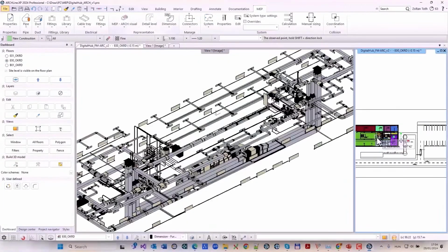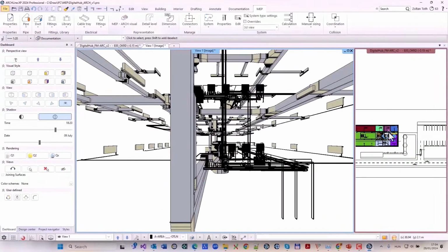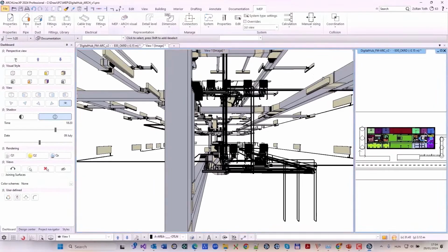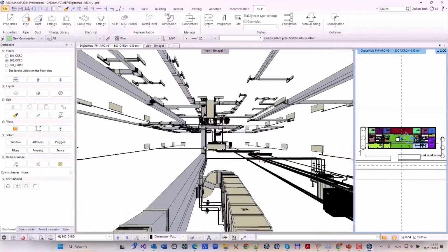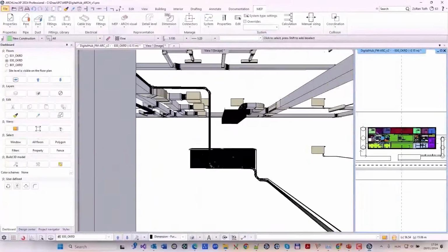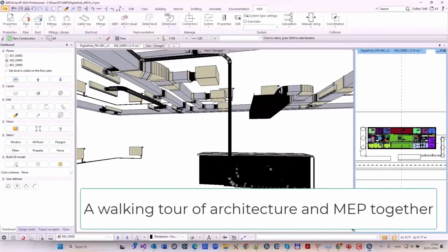Using the Walk tool, you can navigate through a model as if you were walking through it. To walk through the model, drag the eye marker on the direction in which you want to move.